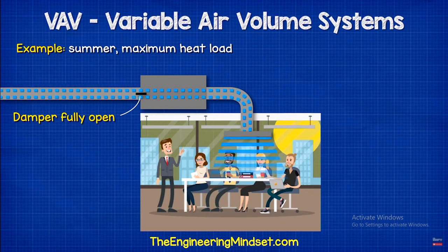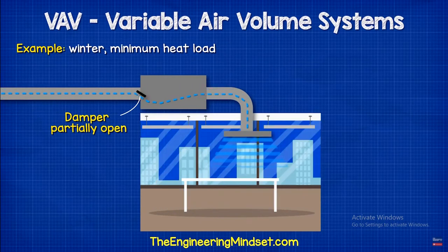This air will enter through the side of the unit and then mix with the main airstream as the damper opens. This is beneficial because we can reduce the heating demand on the reheat coil because we are reusing the heat that already exists in the zone. This also ensures a constant volume through the unit.